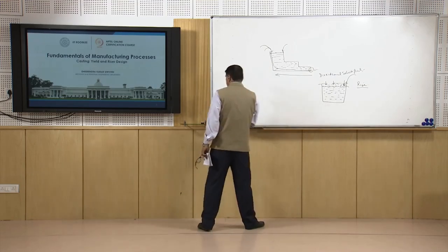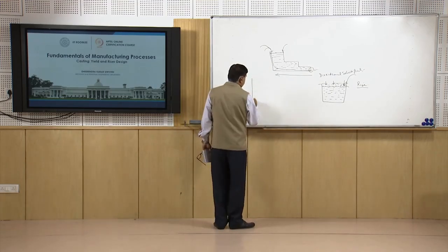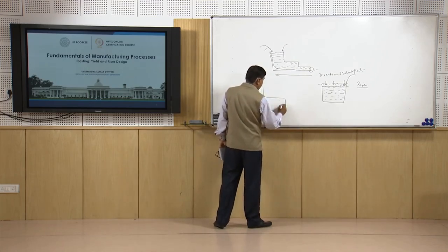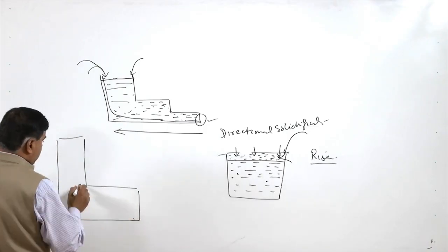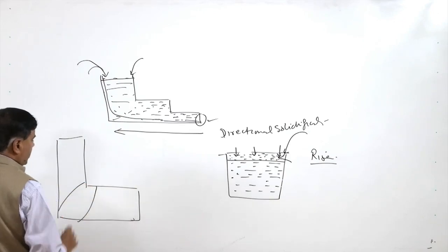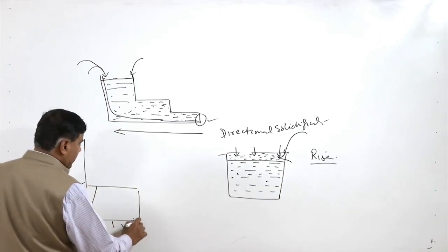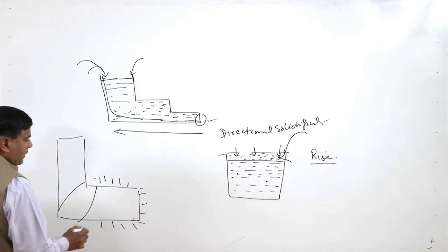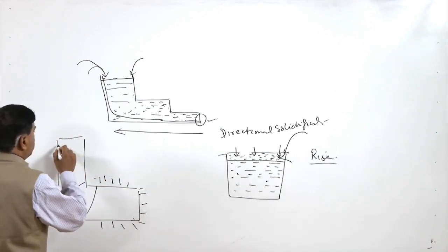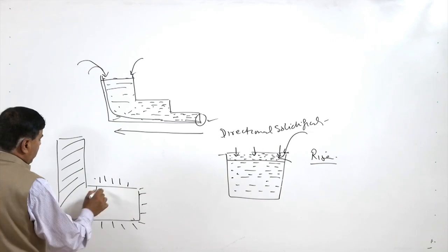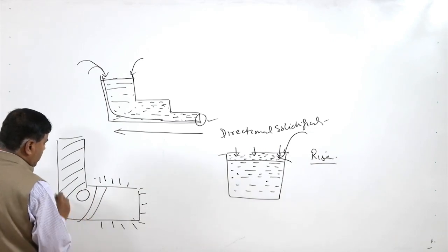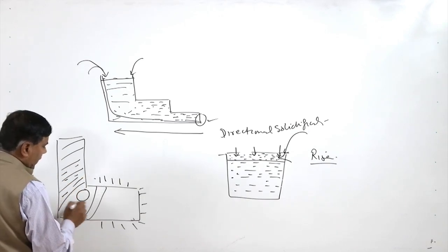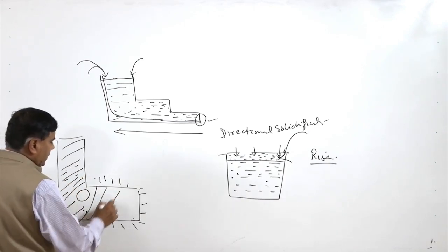Like if the mass of the casting is like this. In this case, the mass of the molten metal in this zone is much more, and in other areas the heat transfer will be causing the solidification, and the solidification will of course be progressing, and at the end here we find that some porosity is left and a shrinkage cavity is left in this area of the casting.